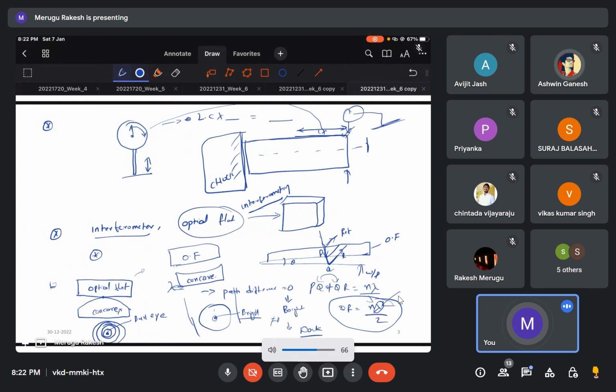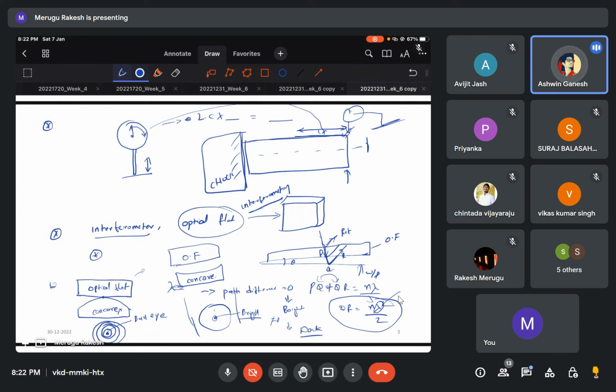Means the other side, which is larger, whereas this Ra value, this CLA value, is the minimum value. No, this root mean square value will be even lesser because you are squaring and taking the square root. I think there is one sequence I can give you in the next class. I don't remember exactly now. I'll give the sequence. But Hmax, I'm quite sure, is the final one which has the higher surface roughness.